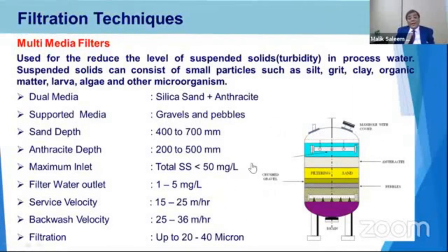Similarly, multimedia filters are used like sand filters. This is the same behavior, but in this case, we have an additional media bed, that is anthracite. Basically, the objective of this multimedia filter is to increase the filter runtime, because in the sand filter, all the settlement or retention of suspended solids will remain on the surface of the sand.